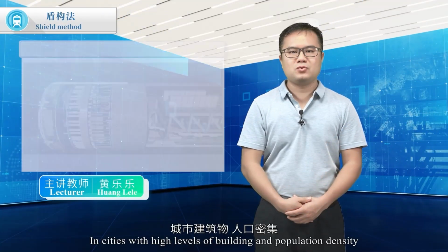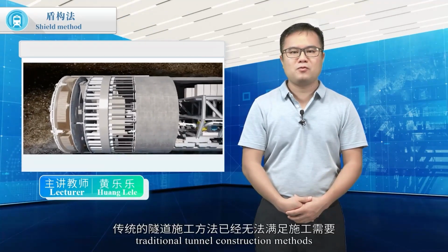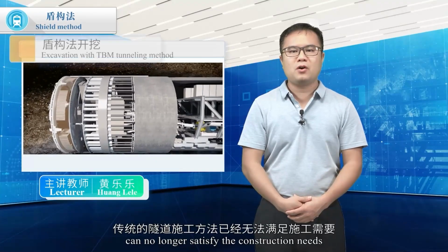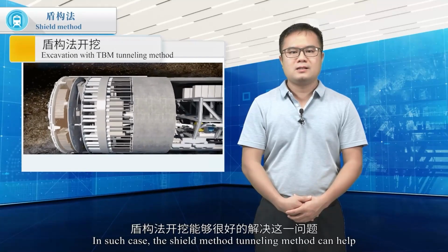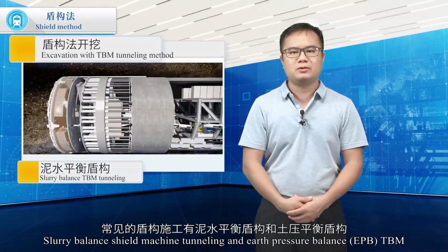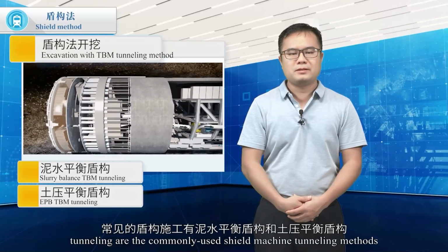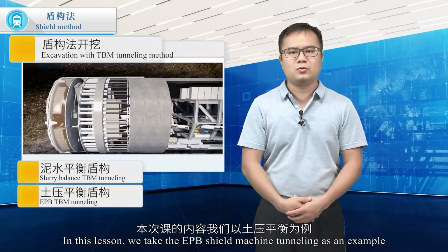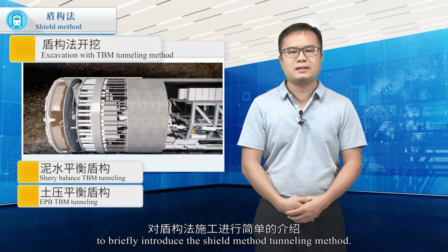In cities with high levels of building and population density, traditional tunnel construction methods can no longer satisfy the construction needs. In such cases, the TBM tunneling method can help. Slurry balance TBM tunneling and earth pressure balance TBM tunneling are the commonly used TBM tunneling methods. In this lesson, we take the EPB TBM tunneling as an example to briefly introduce the TBM tunneling method.